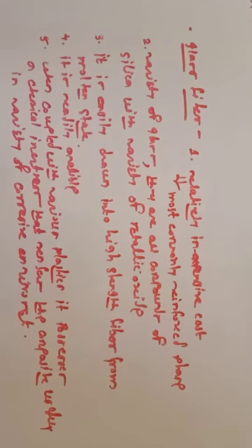So these are some important reasons why this glass fiber is so important, or why it acts as a popular reinforcing material for formation of composite: because it is easily drawn into high strength fiber from its molten state, it is readily available, and when coupled with various plastics, it possesses the chemical inertness that renders the composite useful in a variety of corrosive environments.